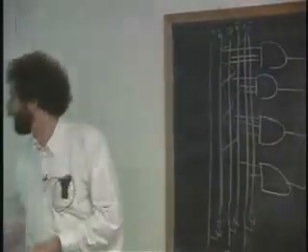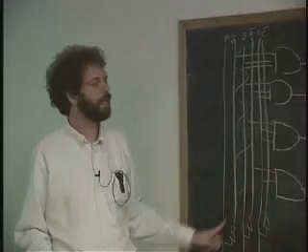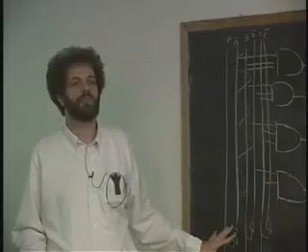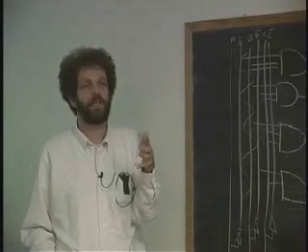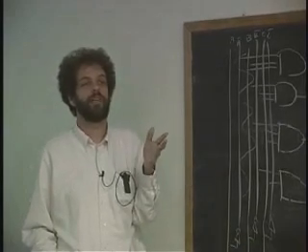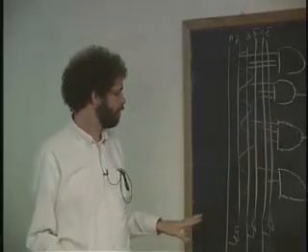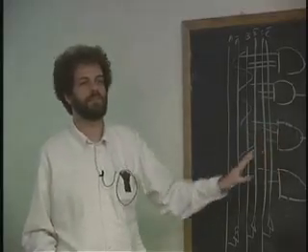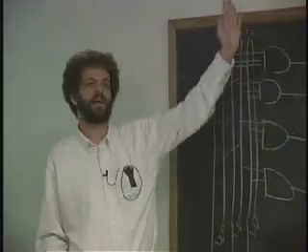If you try to implement the parity function like this, of 3 inputs, you're going to need 4 gates. If you add another input, a 4th input, how many AND terms are you going to need? Parity of 4 inputs. Well, there's 2 to the 4 combinations, right, which is 16, half of which are going to be 1, and you can't simplify it. So how many gates do you need here? 8. Okay, great. 5 inputs. 16. 6 inputs. 32. 7 inputs. 64. The number of AND gates here begins to grow really fast.